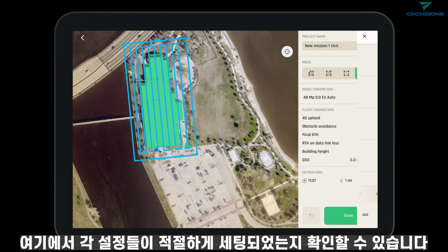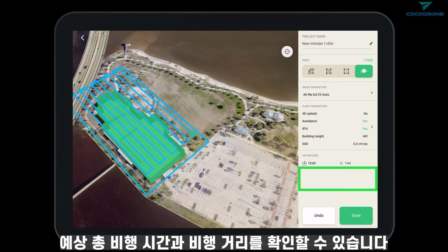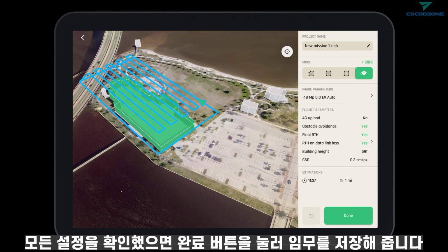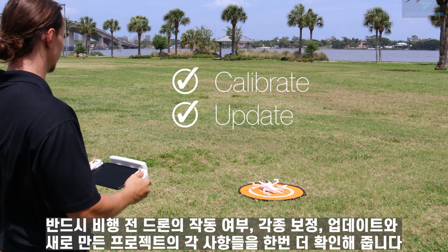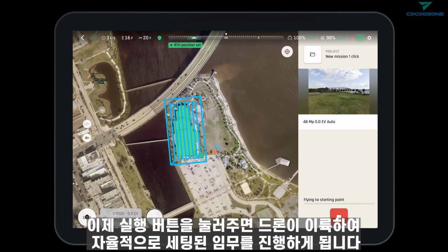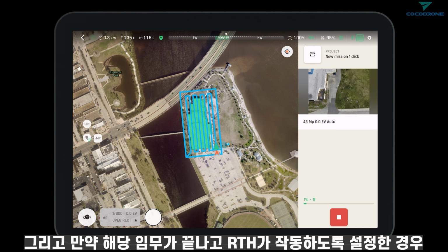Here, we'll look over and make sure that all of our settings are where we'd like them. We can also see an estimated flight time and an estimated flight distance. Once we've confirmed all the settings, we can hit the Done button, and this will save our mission. Before flight, remember to calibrate, update, and ensure your aircraft is functioning properly. Now, all we need to do is hit the play button, and the aircraft will take off and fly the mission autonomously. And, if you set it to, return to home at the end of the mission.